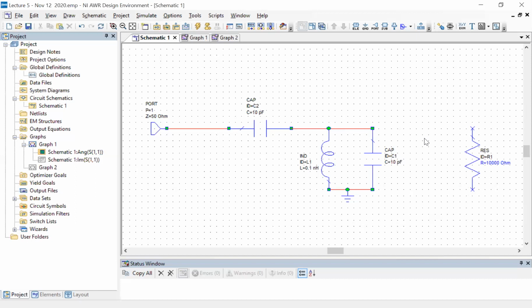And all of these are ways where you are not introducing any internal dissipation, which means that any signal which comes from the port goes back, which means in the magnitude response of the gamma, you're not going to see any response. It's going to be flat. And the information is still going to be in the phase or the real and imaginary parts, if you want to look at it that way.